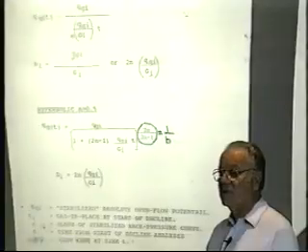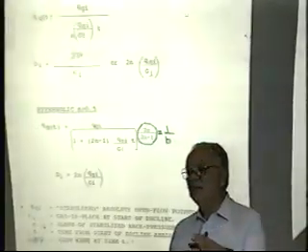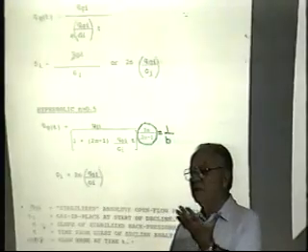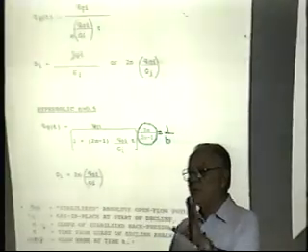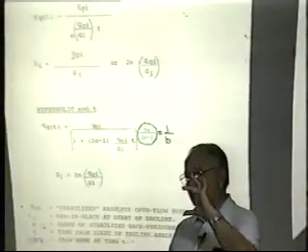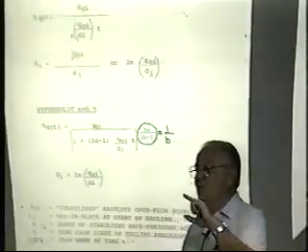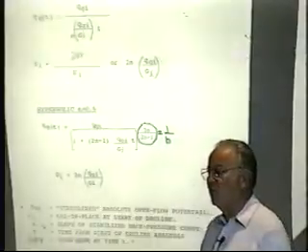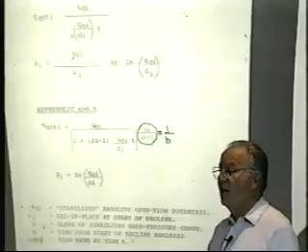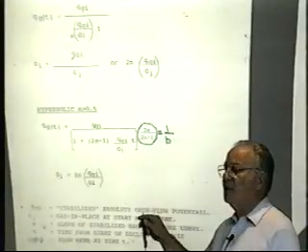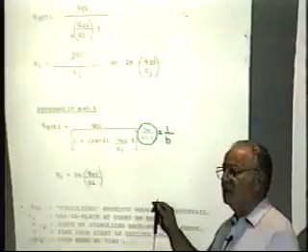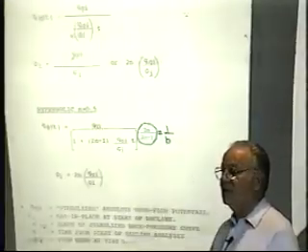To give you an idea where we're coming from, if you have a layered no cross flow reservoir where the properties are such that you have quite a bit of differential depletion between the two layers, when you shut a well in, the pressure you're going to see is the pressure of the more permeable layer. You never see the other pressure. So when you're trying to do a history match on that pressure, you're assuming implicitly that's the same pressure that exists in the other layer, and it isn't true.